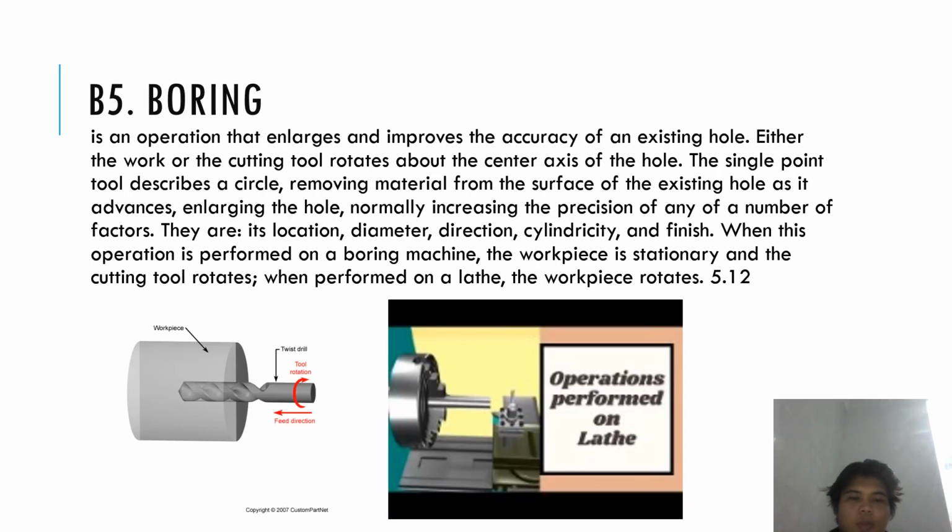Now boring. Boring is an operation that enlarges and improves the accuracy of an existing hole. Remember that it is totally different from drilling. The difference is that drilling makes the hole, but boring enlarges and improves the accuracy of an existing hole. That's all. We will continue.